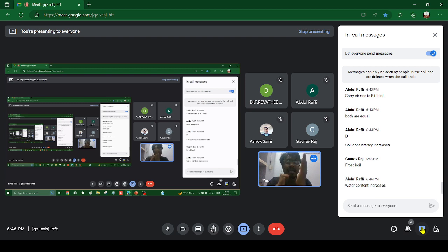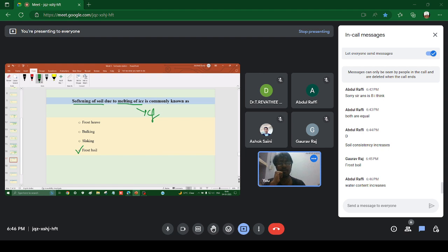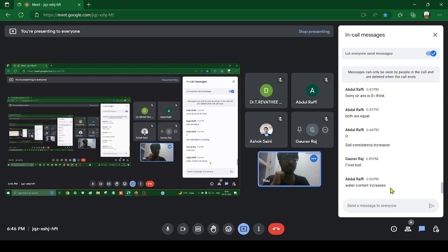If you say consistency in the general term, then the soil can now be deformed with a greater ease because it has softened. But in terms of consistency index, if you say the toughness increases due to an increase in the consistency index, then I will say that the consistency has reduced and liquidity has increased.